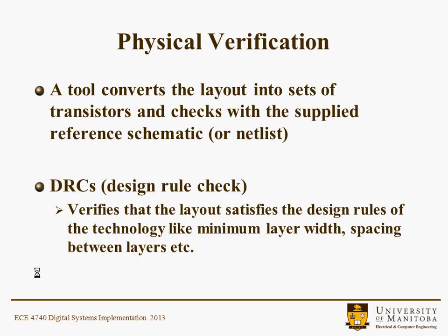There's also electrical rule checks that could take place where you're making sure that perhaps you're not pushing too much current through particular netlists, or making sure that you have large enough power and ground rails to supply the power to the chip. Remember, these ASICs typically are extremely power hungry.